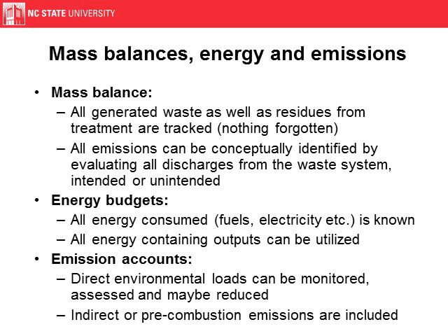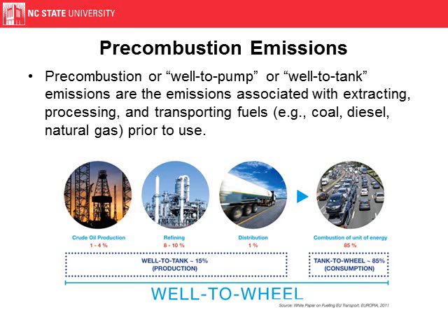That's the mass balance. So whenever we're doing the mass balance, the general idea, like all mass balances, is to track all the weight, all the mass in and out, don't forget anything, as well as all the emissions and the energy being consumed and used in each process, and tracking that all the way back throughout your entire system boundaries.